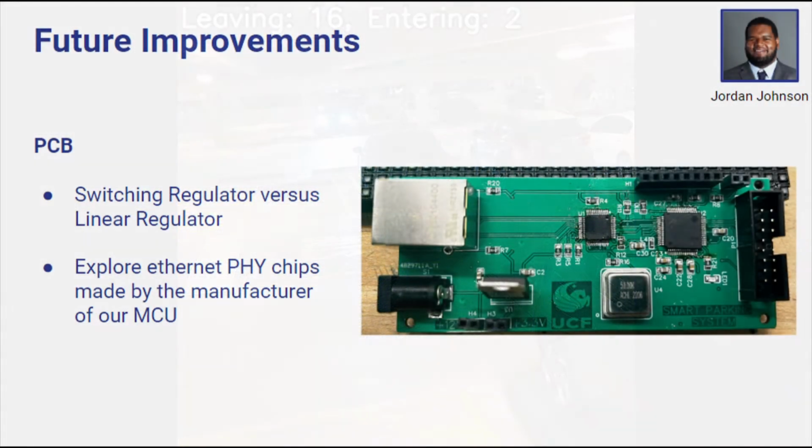Now that we have shown you a demonstration of our system, we will now go into future improvements of our system and begin with the PCB. If we were to make changes to the design of the PCB in the future, we would consider using a switching regulator rather than a linear regulator.